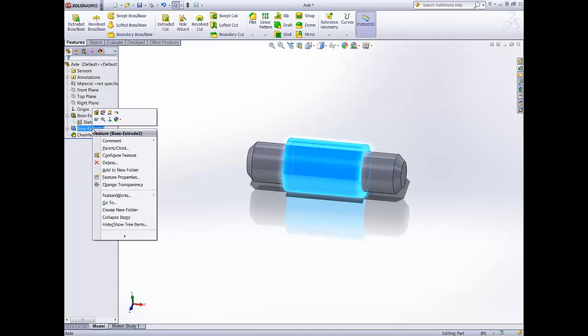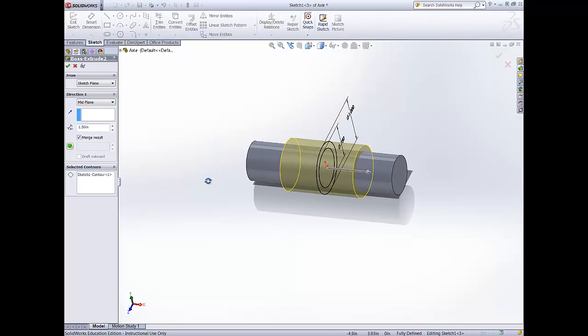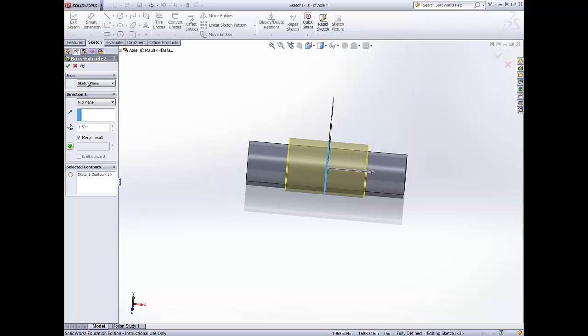Then I'm going to check the second extrusion here, and I'm looking for a value of 1.5 inches. As I look, that value is there, and yet we're still not quite getting the value that we intended. So that means if my axle is done correctly, then there must be an error in the drawing of our axle, or the wheel, excuse me. There must be an error in our wheel drawing. So we've got to go back, find out where that error occurred, and fix it.